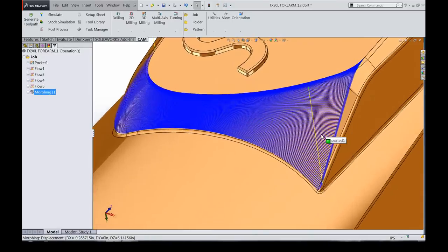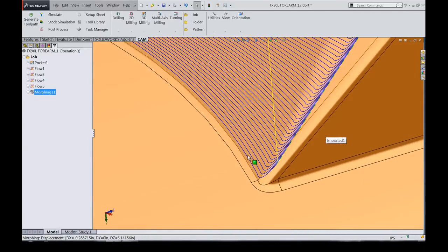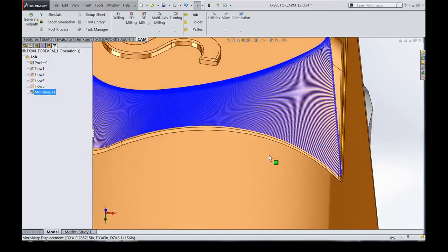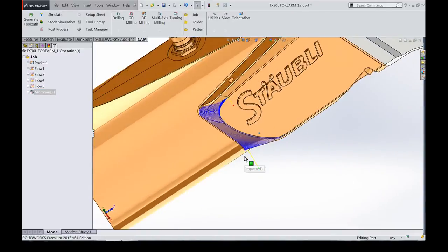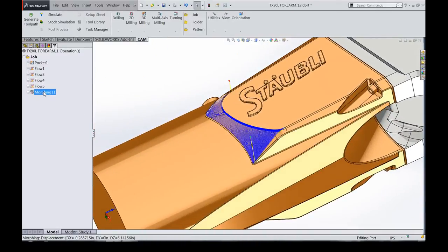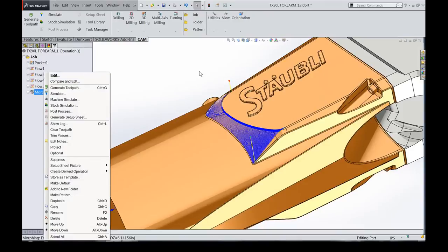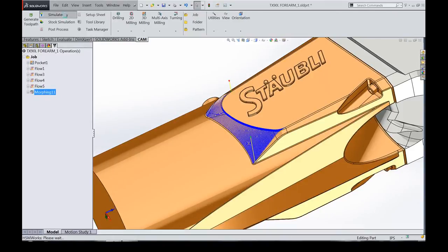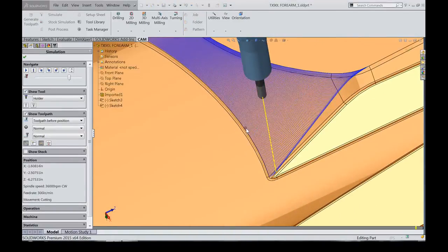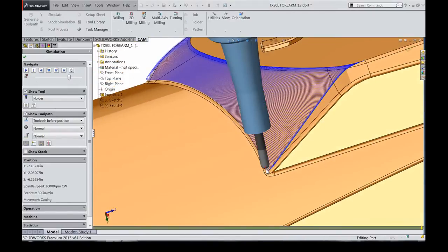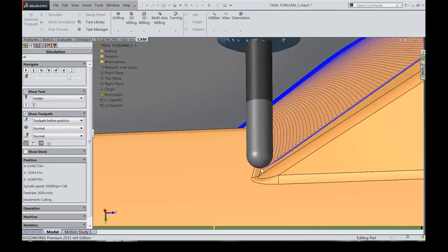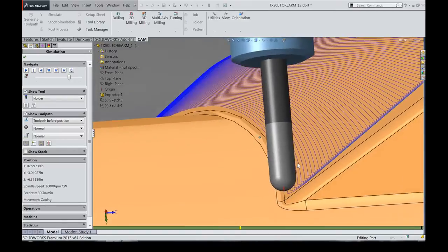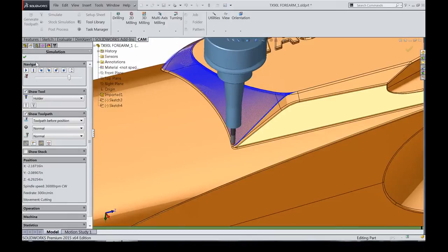Boy, look at that. Now we got something pretty ugly there. We got this really odd collapse because now it includes this. So like I said, garbage in equals garbage out. You have to feed it a clean sketch. And then I guess the last thing too is that this here is not going to fill in the area because we're using this curve. And so the contact point, when you use that curve for the center point, is somewhere up here. So it's just not even going to fill it in. So that's some stuff to remember.